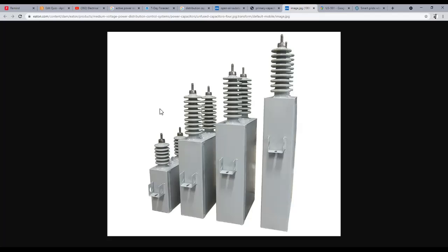What we would do is take a shotgun stick with a piece of copper on it, about 2 feet long. Hold the copper with the shotgun stick, and we just bump both of the terminals with our rubber gloves on. Once you've done that one time, put a wire in between them and just make it permanent until you use them. What kind of material are the terminals made of? Usually they're made of bronze.